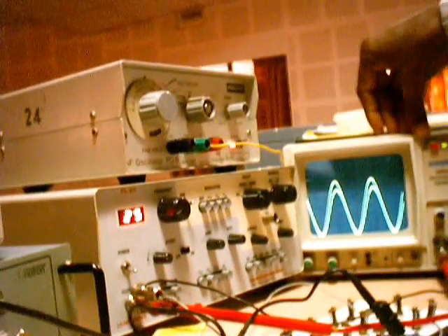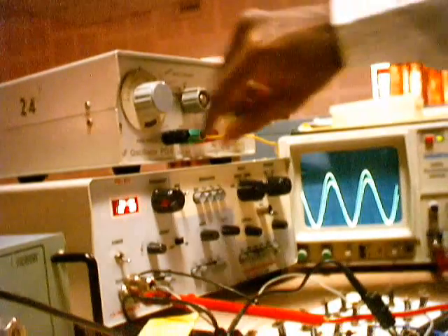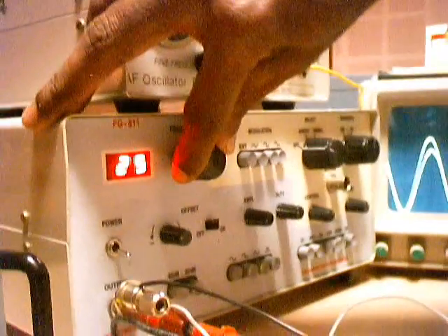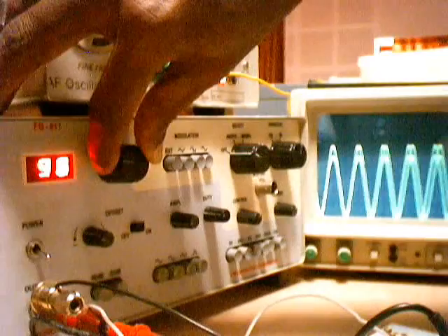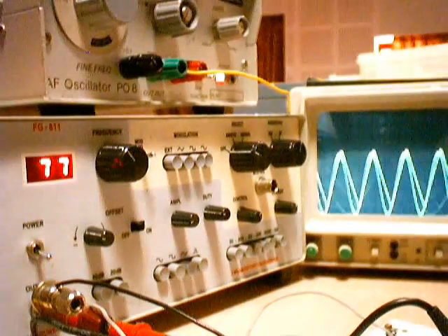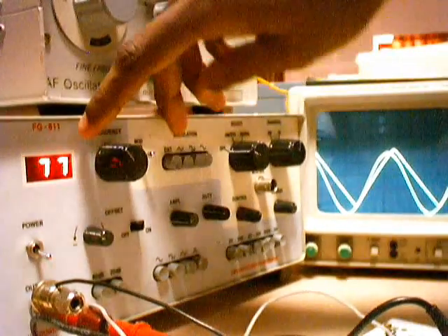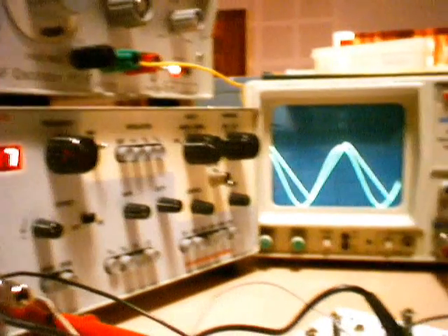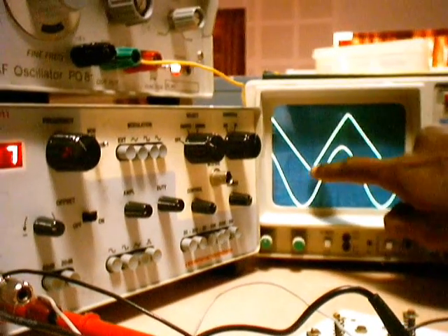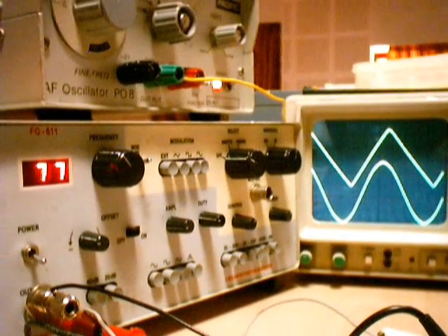While doing this active high pass filter, which involves an op amp, you can see we're going to face a problem while finding the passband gain. If I keep the frequency beyond a certain range, say now I have kept the frequency around 77 kilohertz, you can see the output is distorted. Instead of getting a sine wave, you are having a triangular waveform.